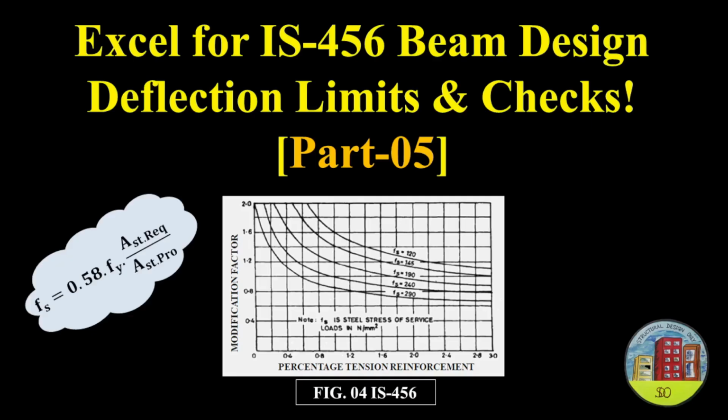In this episode, we'll be deriving the essential formulas to calculate and check deflection limits according to IS456, specifically looking at effective length and the crucial Fs value. Our main goal is to determine the allowable or permissible span for your beam and compare it to the actual effective span to ensure your design is okay.